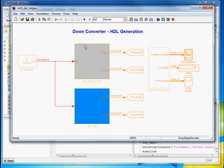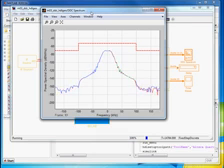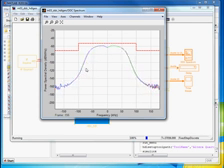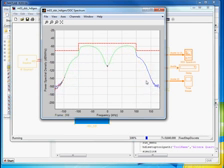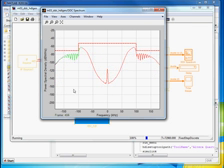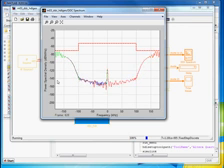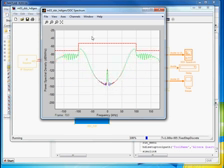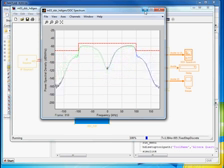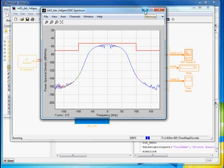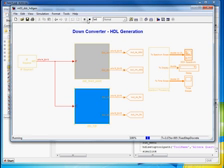So we'll go ahead back up to the top level here and rerun the simulation and compare the results of the two forms of the DDC. We can see that there are some differences as you get out here, but at that point you're 60, 80 dB below the threshold. They're not really relevant, and that represents a reasonable trade-off to make at a system level in the implementation of the DDC. Now we're ready to proceed on to HDL code generation.